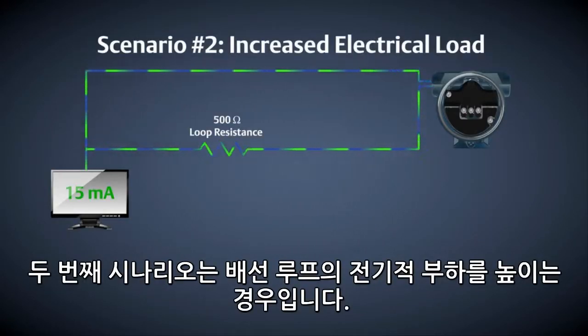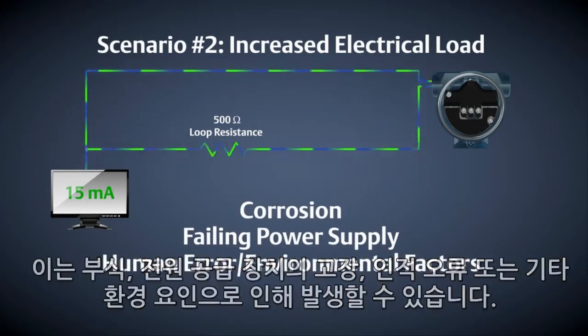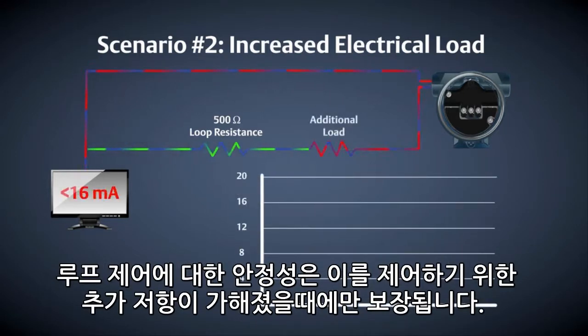The second scenario is an increase in the electrical load of the wiring loop. This can be caused by corrosion, a failing power supply, human error, or other environmental factors. In this scenario, the electrical loop was designed to have 500 ohms of resistance. When additional resistance is inadvertently added to the control loop, the reliability of the control loop is compromised.